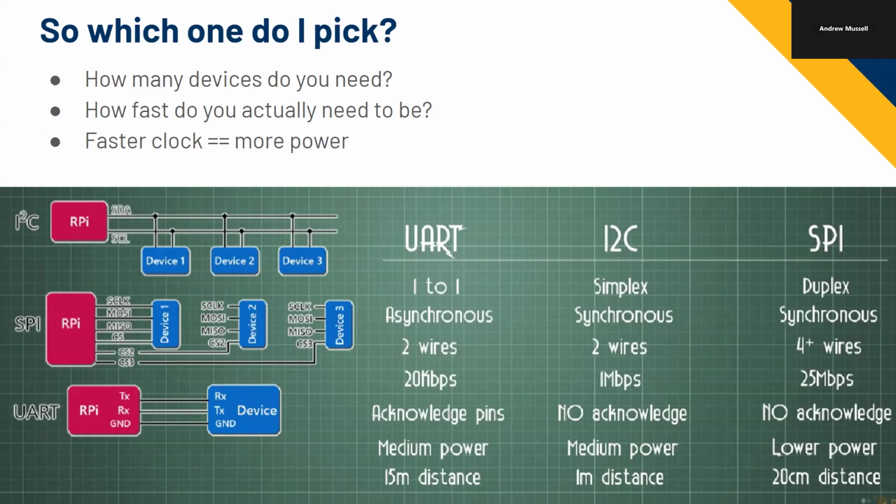doesn't say the device limit, but one of the other reasons, which we'll get to when we talk about push-pull clocks versus open drain clocks, is that the more devices you put on your I2C bus, it'll actually become harder to drive the clock and you won't be able to drive it as quickly. So SPI will be better if you had a big network and this clock line was going everywhere. It would be easier to drive it with the way a SPI bus does, which is why I would lean towards SPI for more devices. But if they're all really close to each other, you could use I2C.